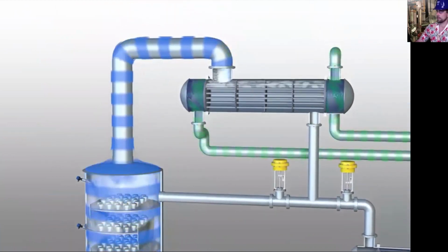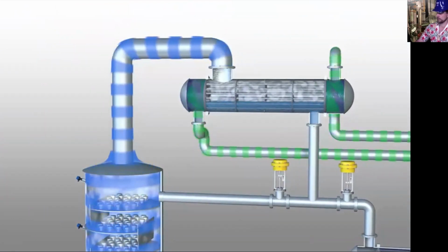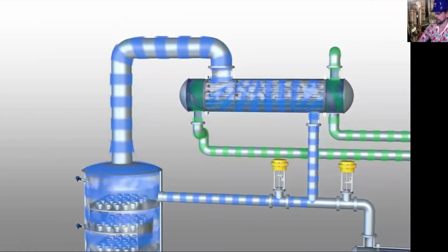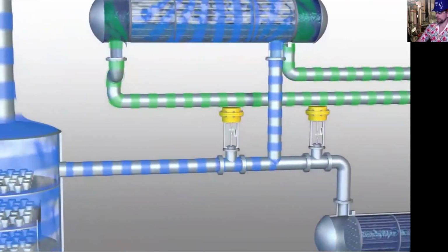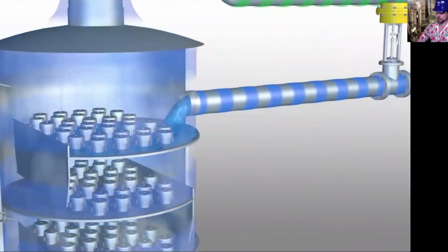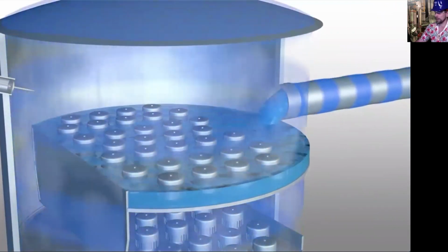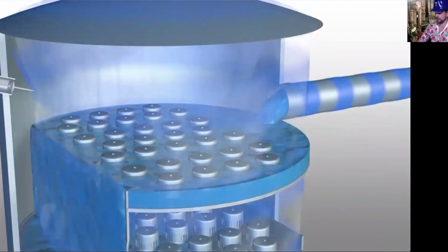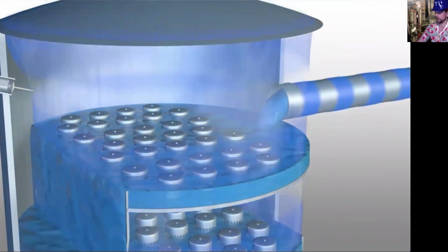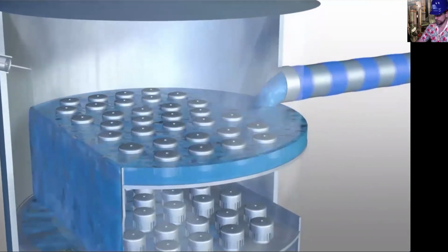And then that vapor enters your condenser for your distillate, which has coolant flowing through it and condenses that vapor back into a liquid. Based upon this control valve, we have it set to full reflux. The purpose of that is that as we're starting this column, we want to fill the trays at the top so that every tray has contact between the liquid and the vapor. Again, we'll explain the importance of that as we move on.